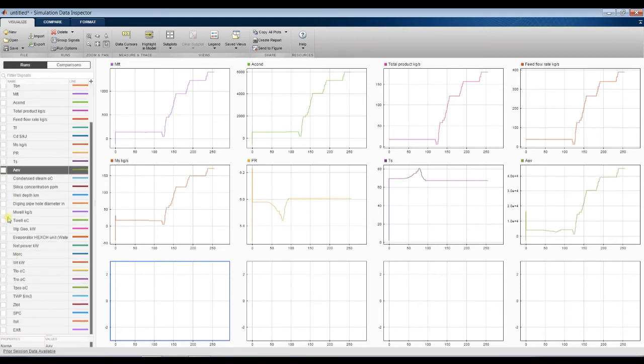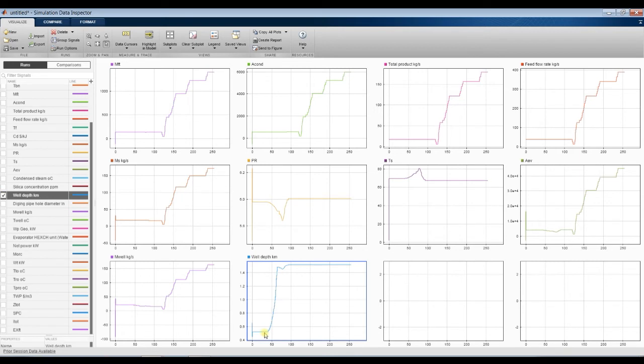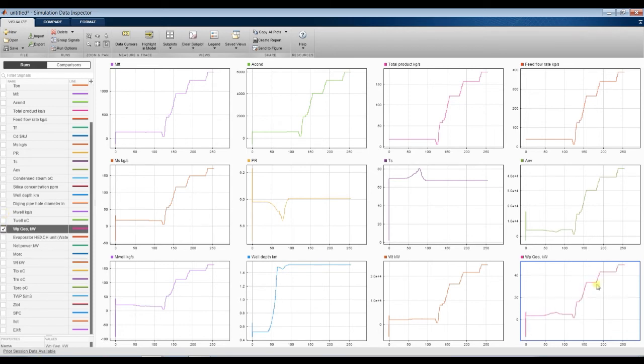This is with well depths. This is the mass flow rate through the well, and this is the well depth. Increasing the productivity would increase the well depth, and decreasing the productivity would decrease the well depth, and so on. Sure, as for the power from the turbine unit, if you need more power, you have to dig more. And this is the power from the turbine unit, and this is the pumping power, the geothermal pumping power.